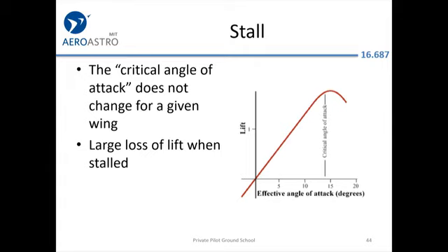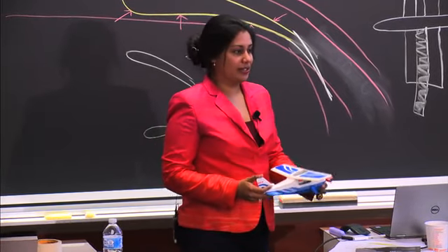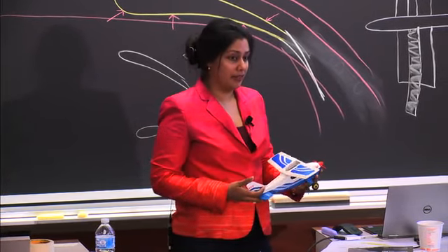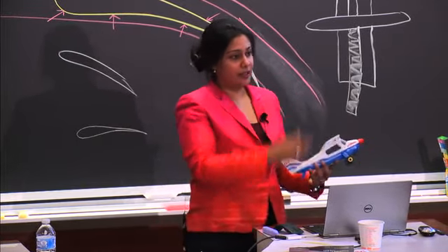And again, once you have that angle of attack too steep, then there's a very significant loss of lift, which is not good when you're flying an airplane. So when can you stall? At any airspeed and any power setting, and it's really based on the angle of attack. So if you, yes, go ahead.